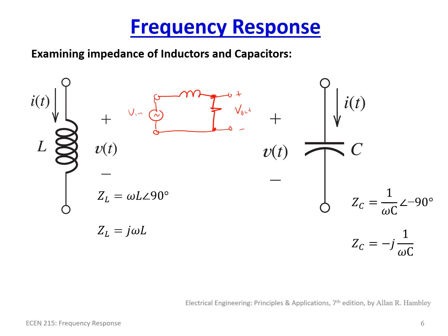Well, in everything we have talked about so far in AC signal analysis, omega was constant. Like we just talked about a moment ago, we had this at 100 pi, which would be equivalent to 50 hertz. And again, just for review purposes, omega is equal to 2 pi f, where f is frequency. So if f is equal to, say, 60 hertz, this would be equal to 2 pi f, so radians would be 120 pi. This is something that's easily overlooked if you're in a hurry, so make sure that you pay attention to that.